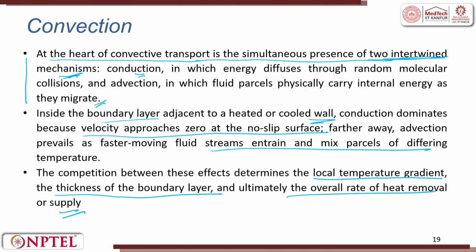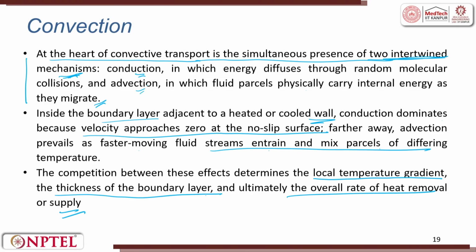At the heart of convective transport is the simultaneous presence of two intertwined mechanisms. One is conduction, you know conduction: hot rod, molecule-wise motion, random motion, vibration, collision. And the other one is advection, in which fluid parcels physically carry internal energy as they migrate.